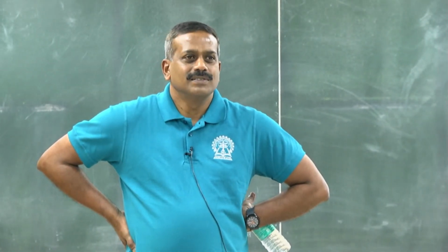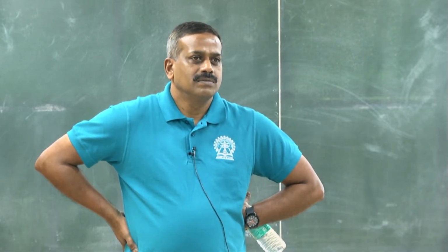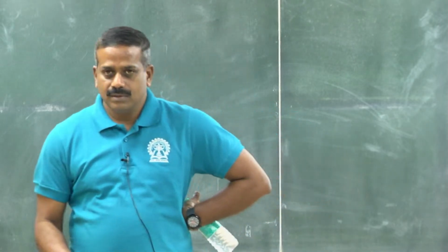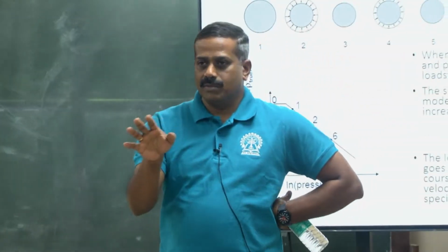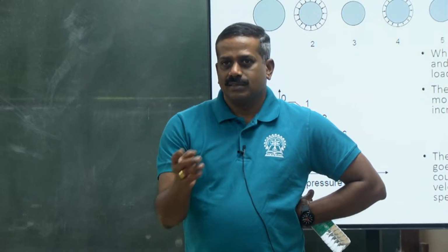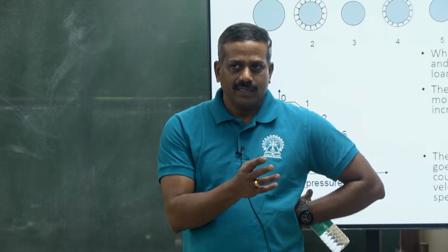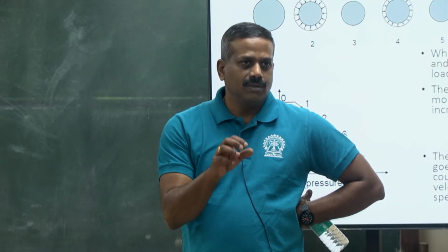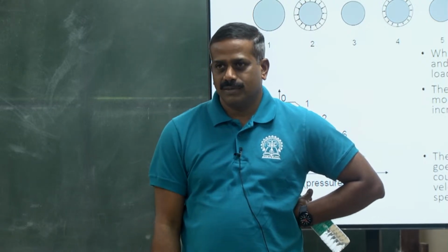Sir, one question. Yeah, sure. For aerated bulk density, should we use this in air classification? Hold on. Before that, I'll come back to that. One common application of why we want to care about void fraction is agglomeration again. When you're agglomerating any type of powder, same thing we talked about binder load yesterday, how much binder you want to add. This void fraction will influence the load of binder that you want to add during the agglomeration process, so that you get good granules.